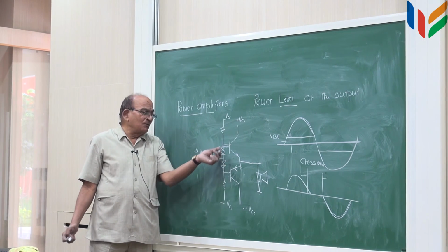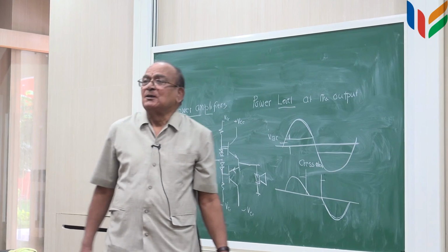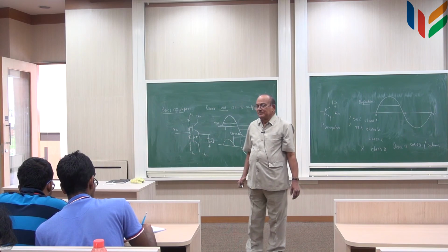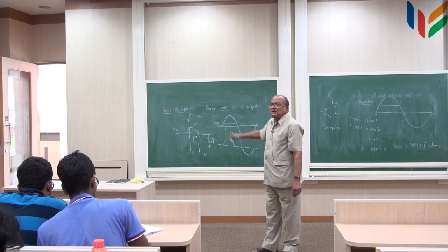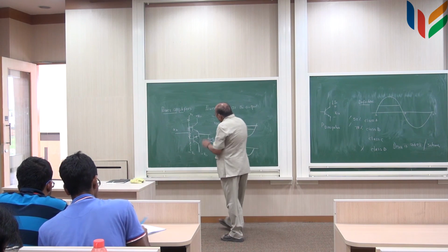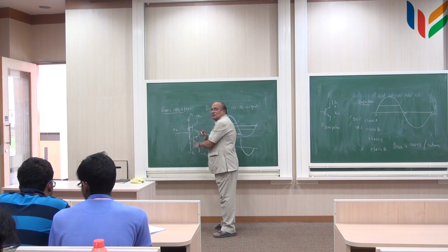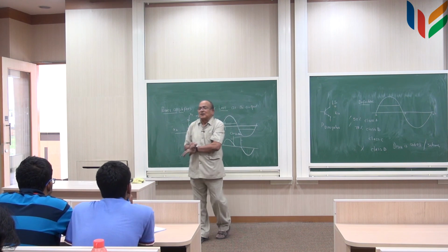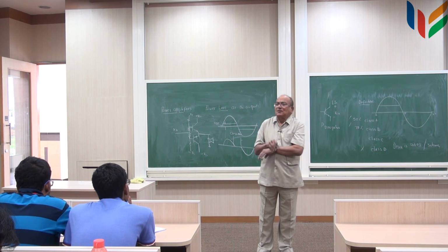To take care of that, you may require more than 1 diode. So, they put 2 diodes in series, a diode chain. But that is a matter of detail, but biasing is done to make a small amount of base current which will be conducting these 2 transistors in the quiescent state. So, they are ready to take on a full sine wave in the full cycle.